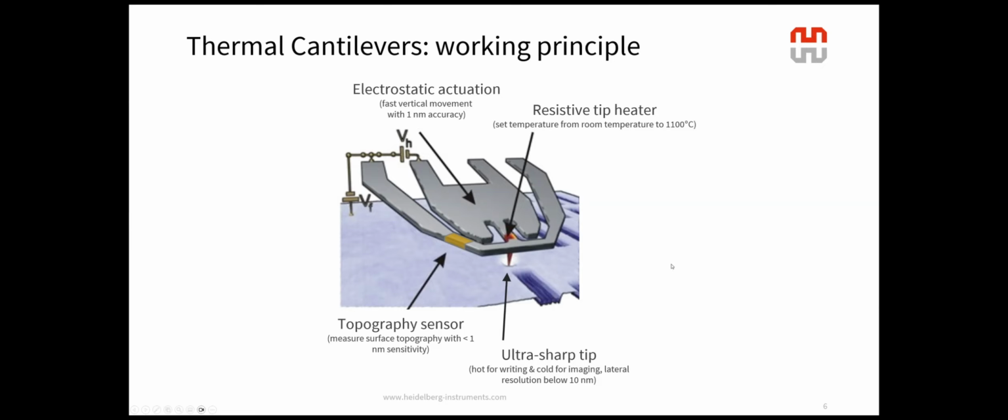This image may allow you to see the cantilevers we're dealing with better in 3D, and we can also see a little more clearly the electrostatic actuation I mentioned earlier. We bend the cantilever by applying a potential difference between this capacitive platform and the substrate onto which we are patterning. So I hope this review will help you have a better idea of the model of our cantilevers.